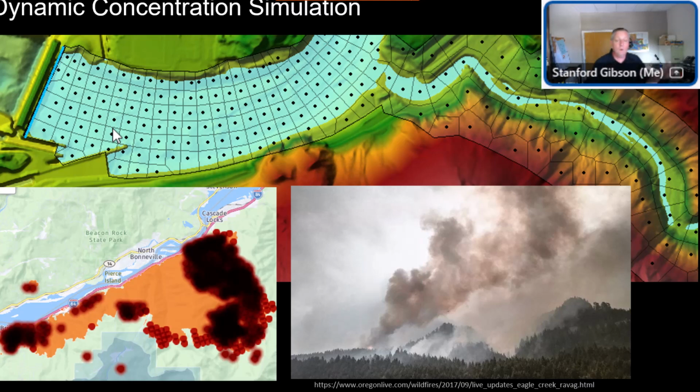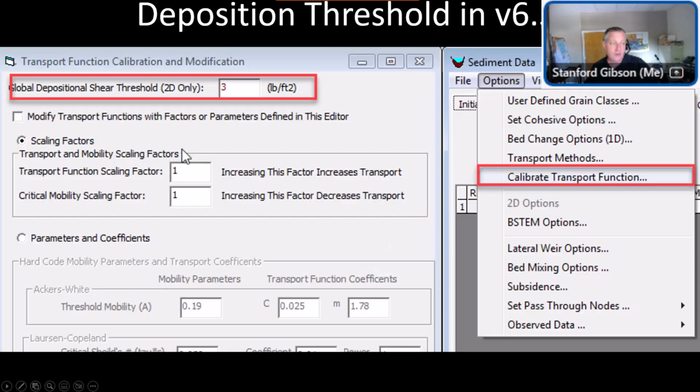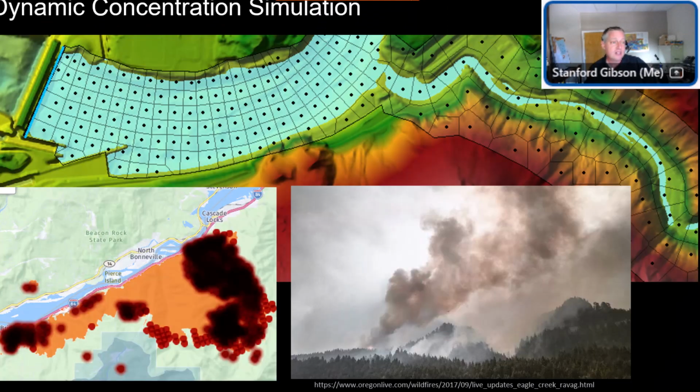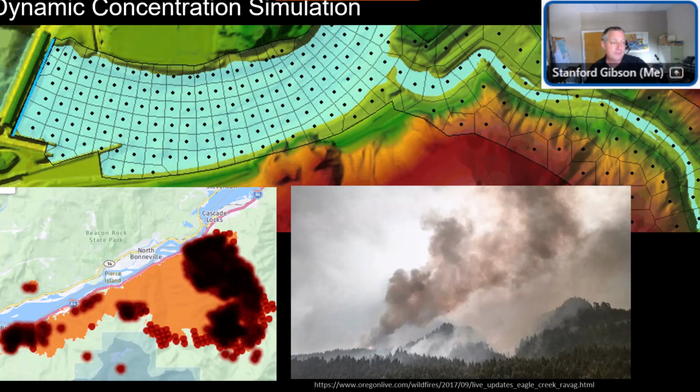And so now, with the concentration-only approach, you can build a simplified sediment transport model, a fixed bed sediment transport model that just moves the sediment down essentially the concrete channel. It doesn't actually work like that yet. Well, I'll tell you about it. But essentially, that's the way I would think about it. You want to move the sediment down this concrete channel, give it the opportunity to deposit as the shear stress decreases, but then eventually, when it hits this water, to disperse and just use the advection diffusion equation to see what happens to it.